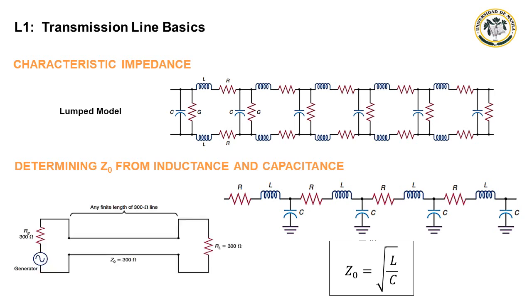If the line, load, and generator impedances are made equal, as in the case with matched generator and load resistances, the criterion of maximum power transfer is met. An impedance meter or bridge can be used to measure the inductance and capacitance of a section of parallel lines or coaxial cable to obtain the values needed to calculate the impedance.